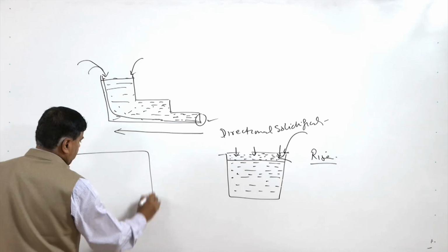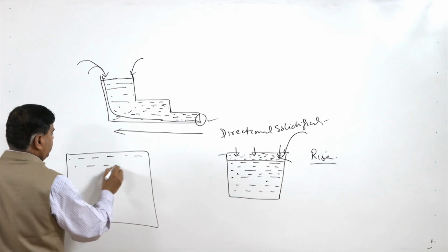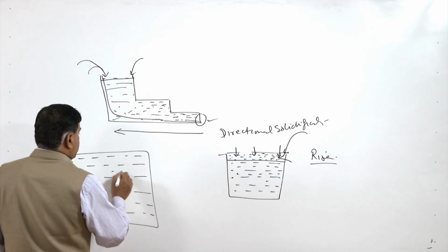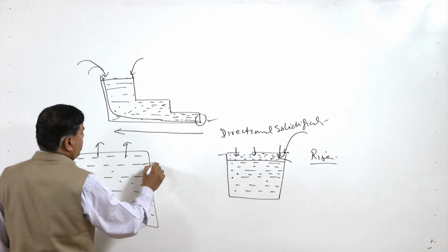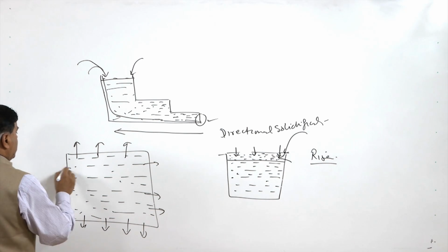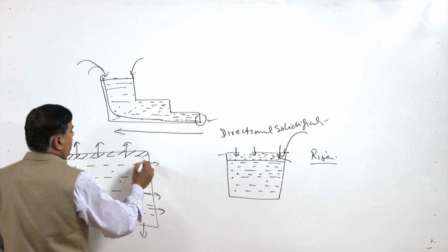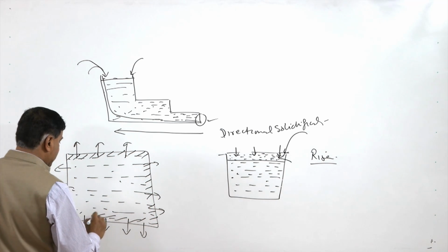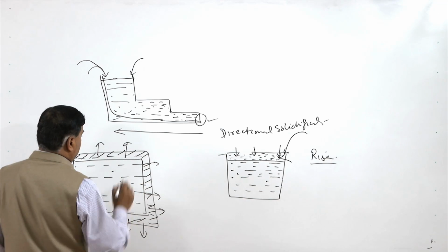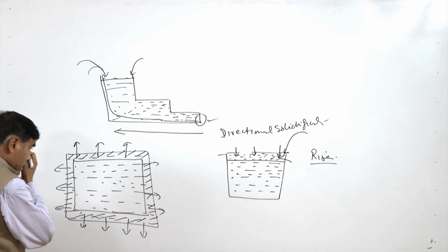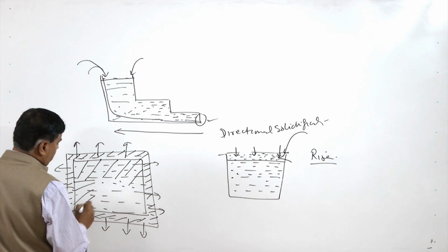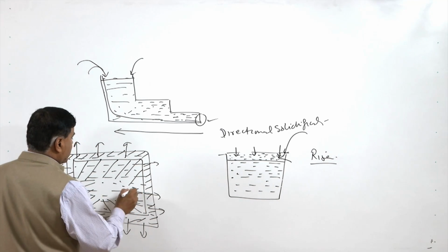Say for an example, this is the mold and it is full of the molten metal like this. So, if the transfer of the heat is taking place from all the sides, all these 4 sides of the mold, obviously, the solidification will be starting from the mold and then it will be progressing towards the center. So, like this. This is the one zone which will be formed next to the mold wall and the remaining will be the liquid metal. So, as the solidification progresses from all the sides, what we will be seeing is that the molten metal will be pushed towards the center.